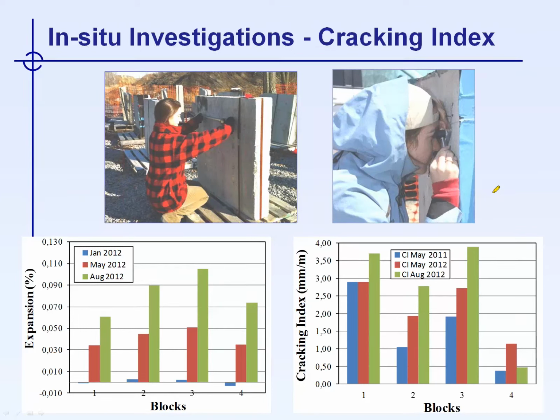This slide is just giving you an example of the use of this cracking index procedure. This is on another project where those concrete elements have been extracted from housing foundations, and there is a process of deterioration in the housing foundation that is also related to aggregate expansion.